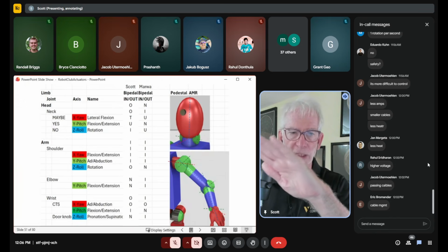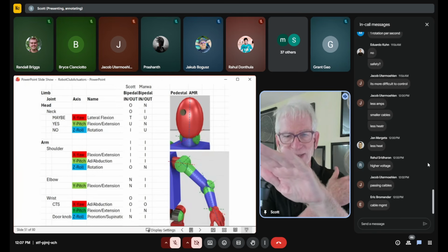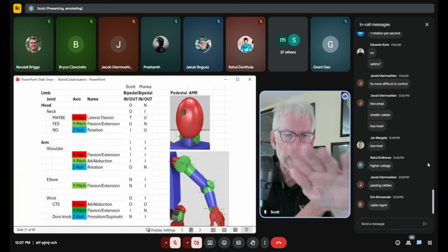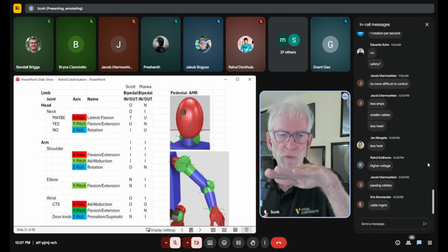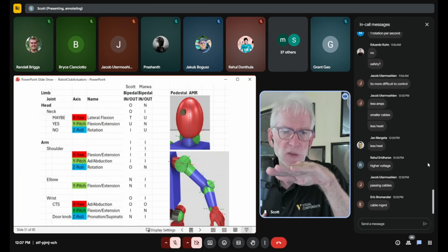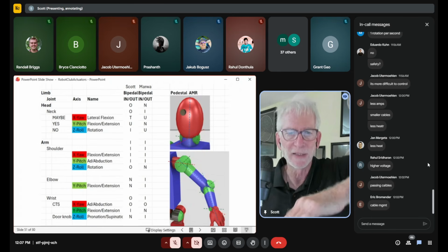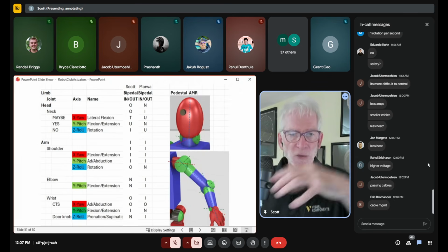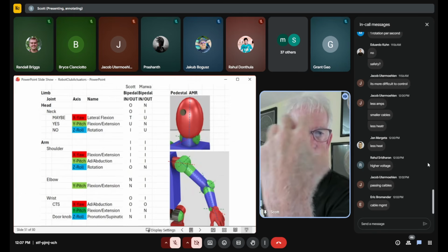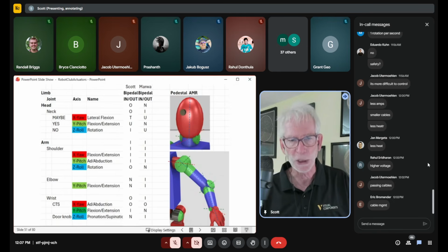And you say, yes, but how do I get my wrist to different locations? Well, that's because you get redundancy in your shoulder. And it turns out that extra axis in your shoulder is what will allow you to get it around. What the extra axis gives you is the ability to keep your wrist at a position and orientation in space by getting your elbow in different positions. So that's why we sometimes call it the elbow redundancy. It allows us to rotate the elbow while keeping that hand in a fixed position, so I can get underneath somewhere to be able to do anything for accessibility. So the redundancy is not about reach, it's about accessibility.